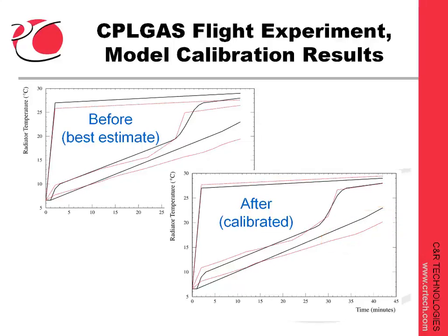Maybe the thermocouple data or location is untrustworthy there, but it's more likely that something is missing from the model, such as non-uniform bonding of the interface pad conductance, or not enough credit was taken for portions of the condenser that cantilevered off the ends of the aluminum plate, or maybe some other uncertainty that was important but wasn't included in this first pass. As you can tell, the drudge work might be automated, but engineering judgment and experience are still important.